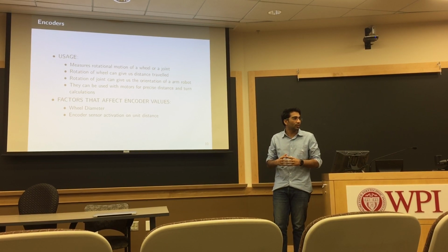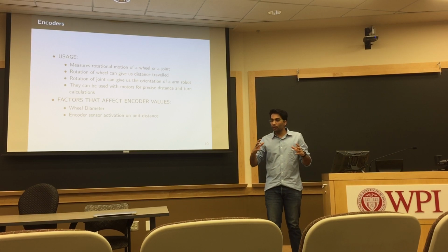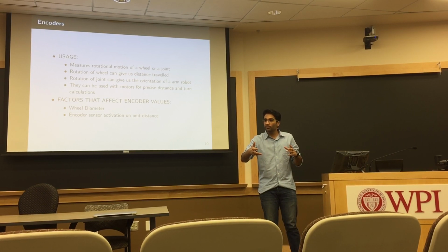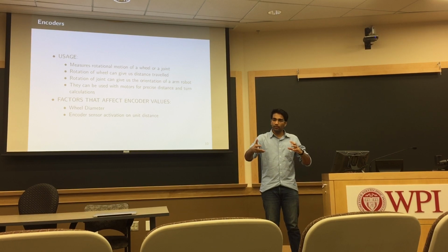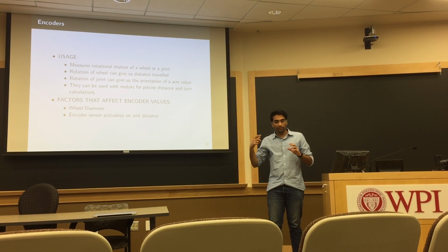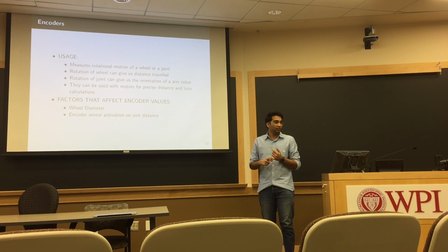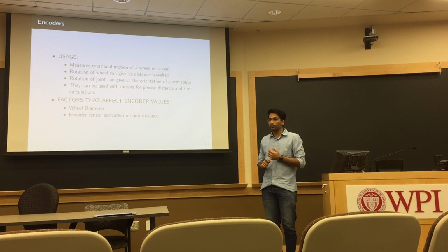Now imagine you have 2 wheels. You have two motors and two sets of encoders. And the right wheel is going very fast, and the left wheel is going much slower. So what will happen? You will turn towards the left side, right? Now using these encoders, the count on the right wheel is more, but on the left wheel it's less. So you can say, just looking at those two numbers, that it's going in the left direction, right? So it's used even in determining the orientation of the robot, correct?